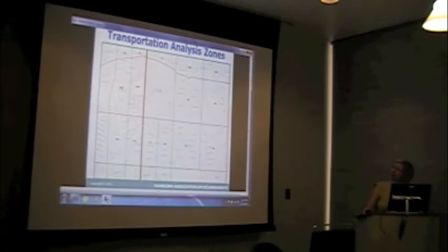So this is the light rail. Now, for modeling transit, there are studies that show that people who are within 1/3 of a mile from transit or light rail are likely to walk. They would often walk and use transit. Those who are 1/3 to 2/3 away, they walk some of the time. And then beyond 2/3 of a mile away from transit, it's hard to get them to walk. So for a good representation of transit, you have to have smaller zones along the corridor. In other words, these people are very likely to walk. These are not so much likely to walk. And if you break them, you have a realistic representation of transit ridership.